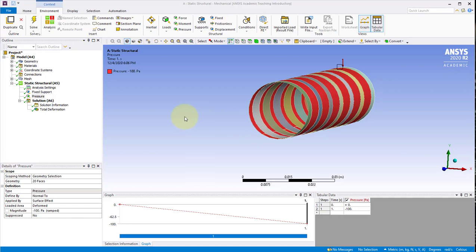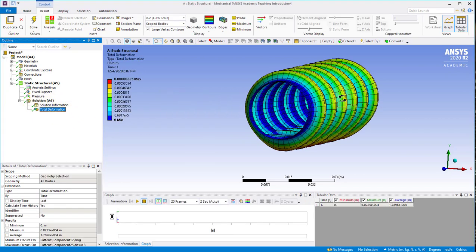And if you try and solve it like this, you'll get your deformation. It'll look like this, which is not right. Because in this case, it's applying that pressure to the outside of the cylinder, not the inside. So the tissue rings get sucked out. Now, that's not right. We don't want that. So I'm just going to go over how to fix that real quick.